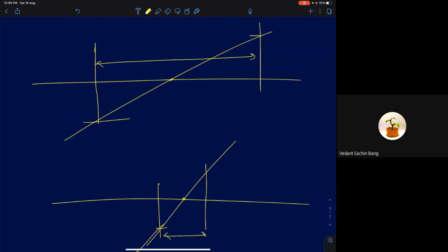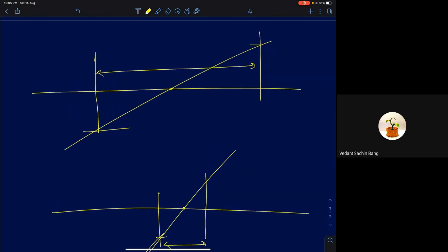Now tell me, looking at these two waveforms, which one will have more false triggering? So this is the low frequency and this is the high frequency one. Which one will have more false triggering? The low frequency one, right, because it's spending longer time traversing this region. As noise is corrupting here, it has longer time to produce unnecessary edges.